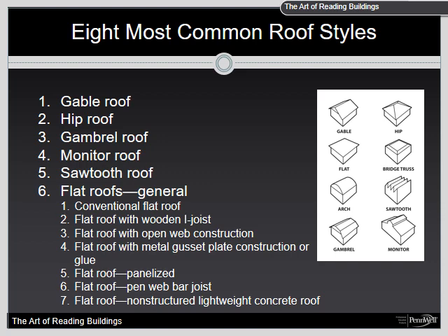Hazards. Extensive use of 2x4s in trusses with the gusset plates equals short burn time and early failure of a roof. As the truss members are under compression and tension, when the bottom quarter webbing fails, one or more trusses can also give way, causing a rapid collapse.